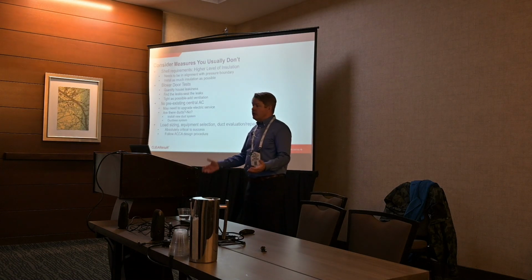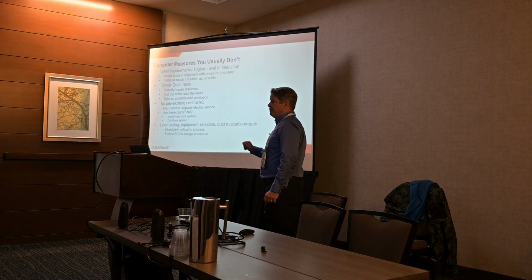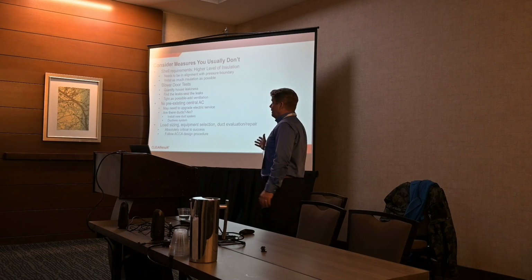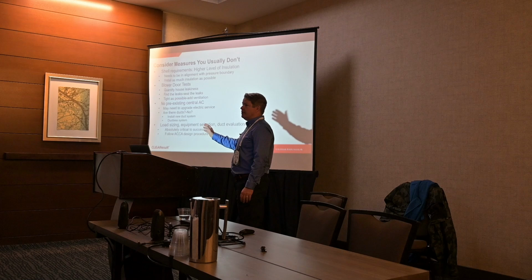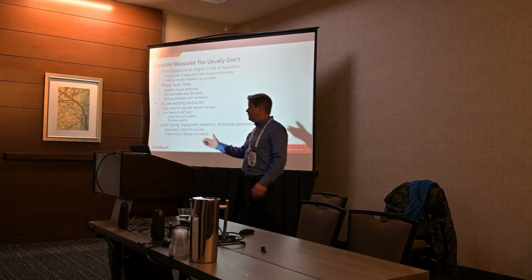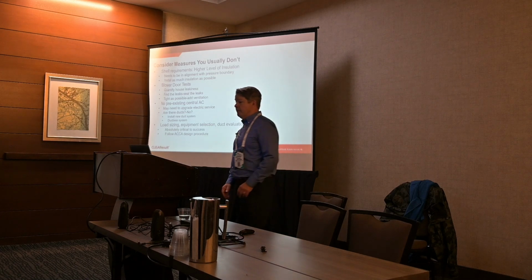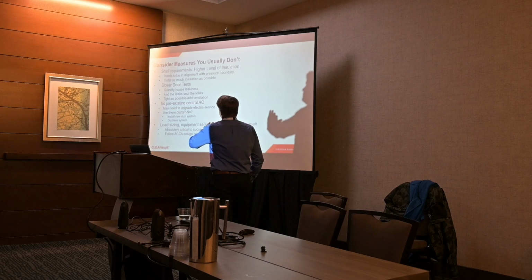The air does flow up there, right, and go out through leaks and stuff, but air sealing takes care of that, right? The insulation is to stop heat loss by conduction. And so there's no reason for the heat loss by conduction from the ceiling to be greater than the walls. It's the delta T that drives that, the difference in temperature between inside and outside. So if we could get R49 in the walls, certainly we would, but we can't, okay? We want to get as much insulation as possible.